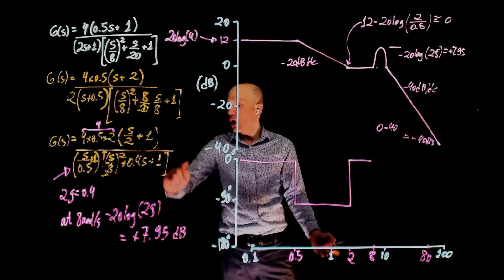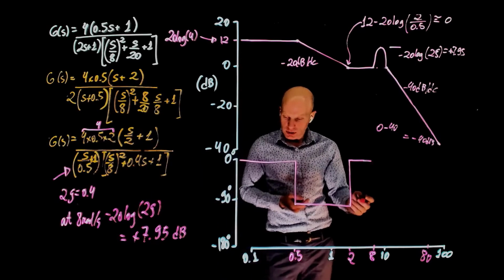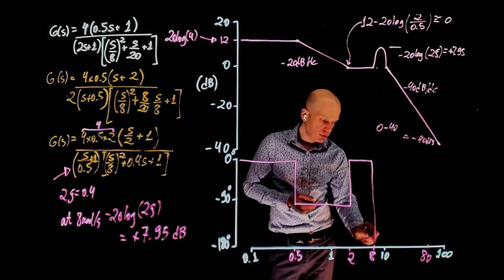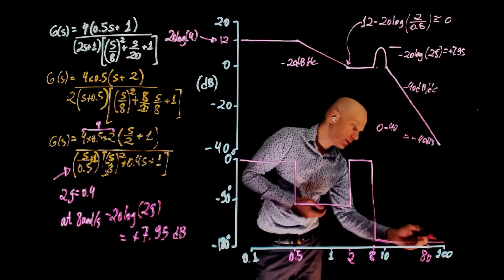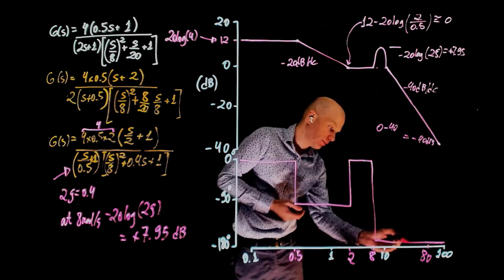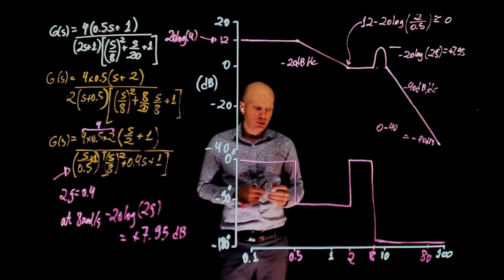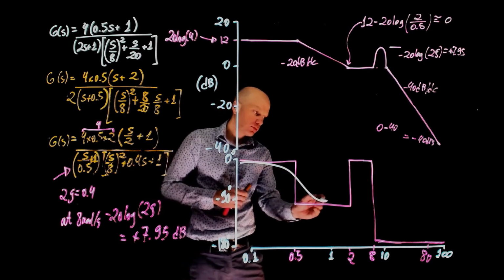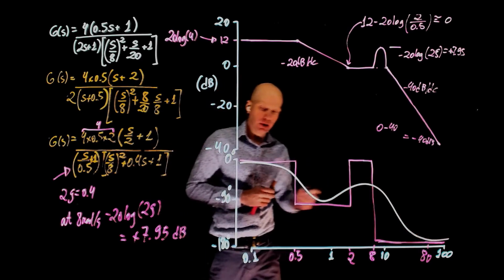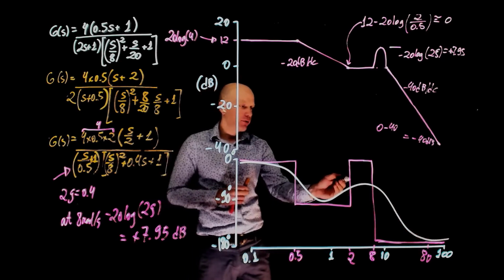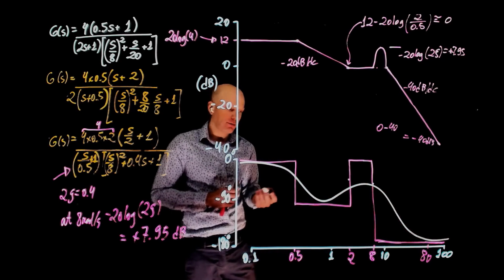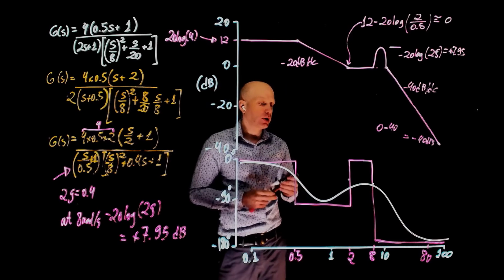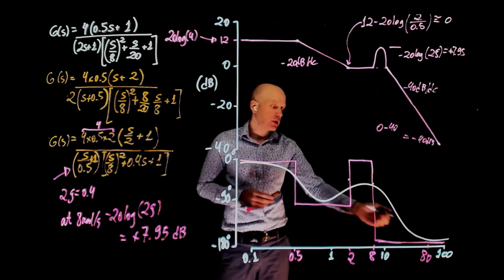8 comes from a complex pole. So the complex pole adds negative 180 degrees. And this will stay at negative 180 as now the frequency tends to infinity. You can attempt to interpolate this. Something like that. Passing by 45, negative 45, and then tending to negative 180 degrees as the frequency tends to infinity.